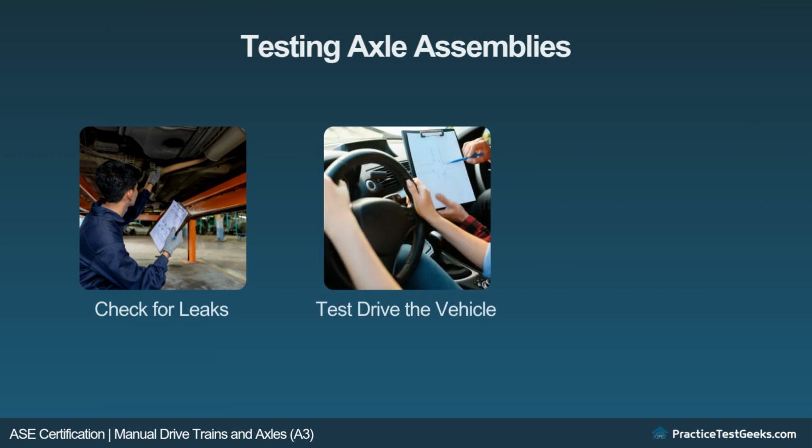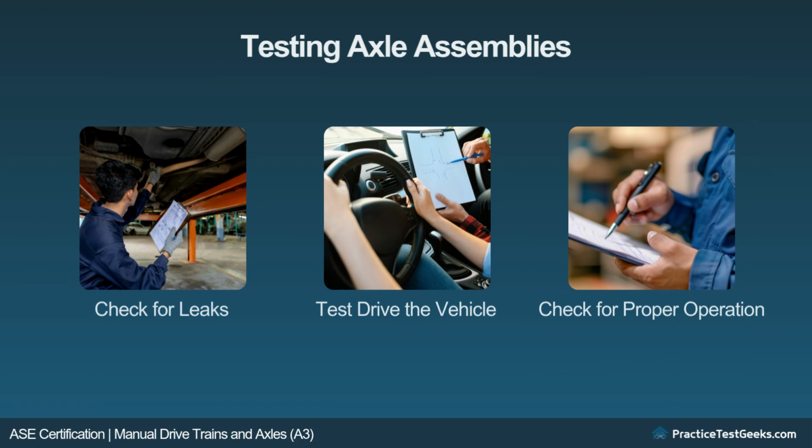Test drive the vehicle. Take the vehicle for a short test drive to ensure that the axle functions properly, without any abnormal noise or vibration. Check for proper operation. Ensure that the transmission shifts smoothly and that there is no noise or vibration coming from the axle assembly.